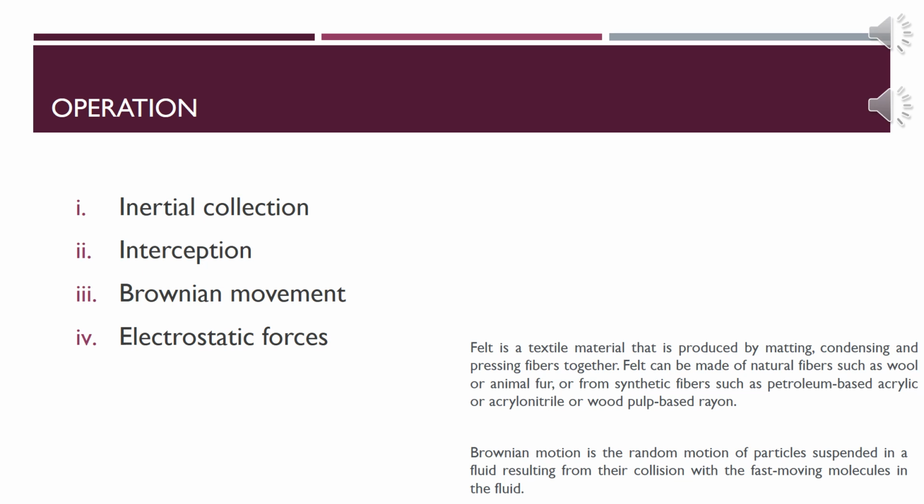Number 4, electrostatic forces: the presence of an electrostatic charge on the particles and the filter can increase dust capture. A combination of these mechanisms results in formation of the dust cake on the filter, which eventually increases the resistance to gas flow. The filter must be cleaned periodically.